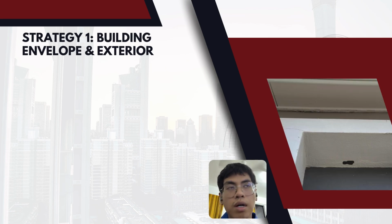Another part of the house would be the external walls outside. The strategy to be done is condition monitoring and crack repairs. So we have to inspect for cracks, peeling paint, and moisture stains, and then seal those minor cracks and repaint the affected areas. The frequency is annually, every year, and this can help to prevent any water penetration or falling debris hazards.